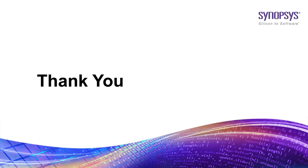All right, thank you, Yervant. Our next question for you: how is repair realized? The repair is typically realized with the memories. We do repair, of course. With other IPs, we have calibration, we have trimming, which I would also consider under that repair umbrella. But let me specifically talk about the memories, since I use the term repair for memories in this presentation. Memories often would have a defective bit, depending on which technology you're using. The more advanced the node, the higher the probability of having failed bits.